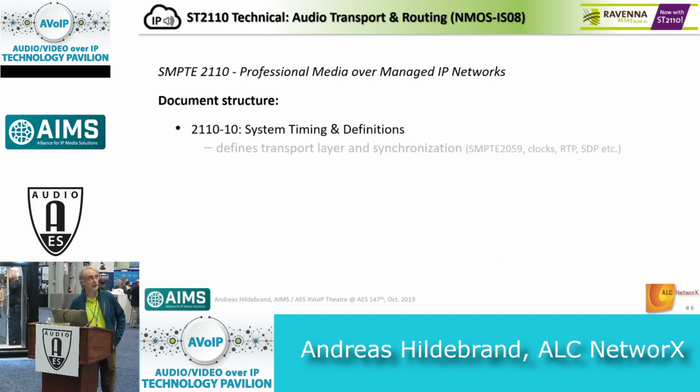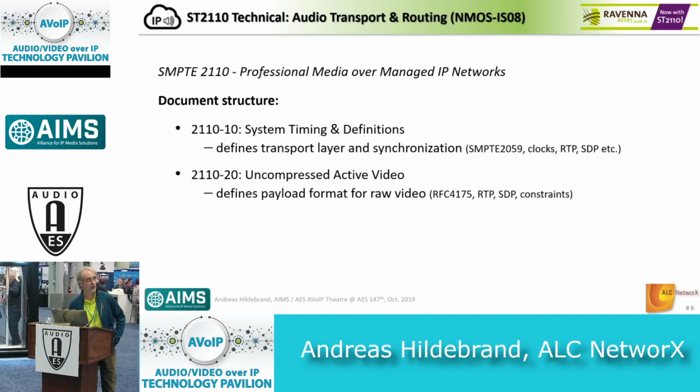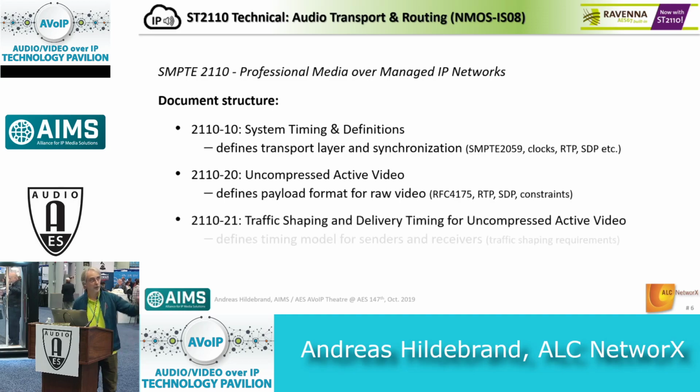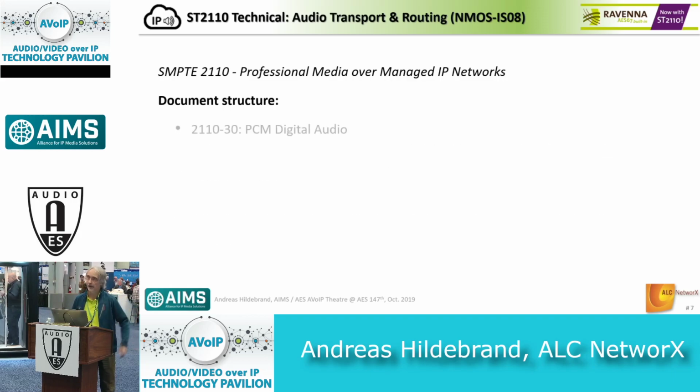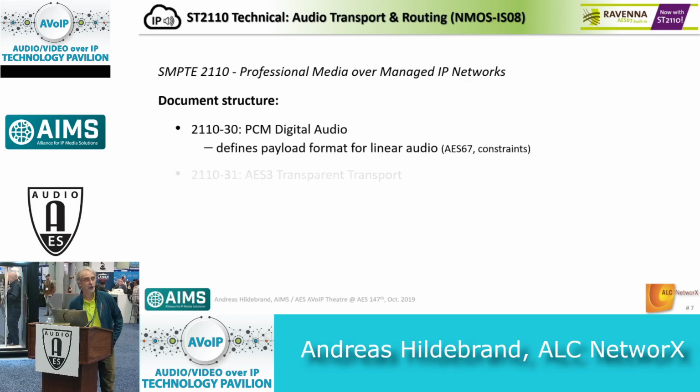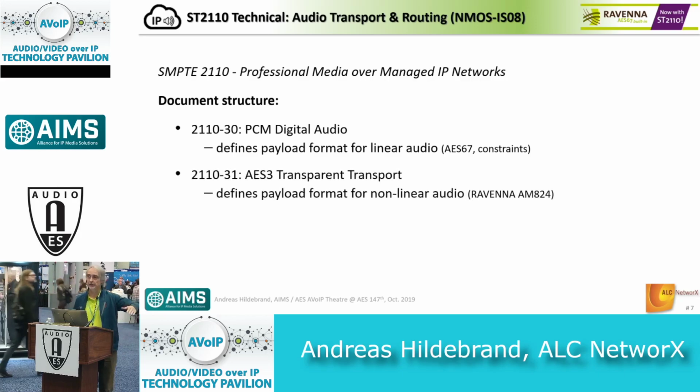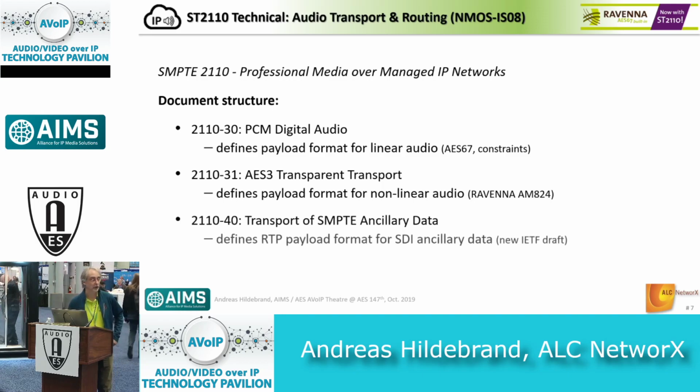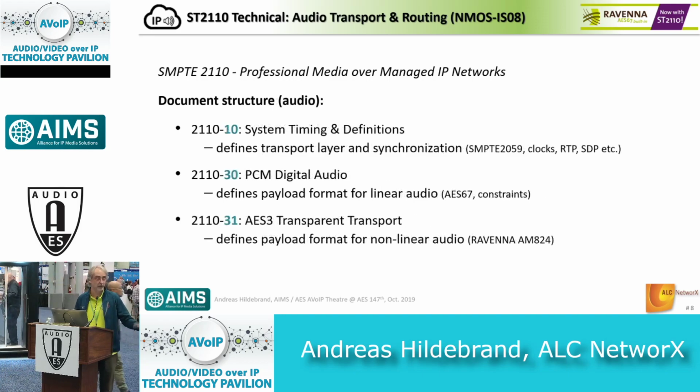So the document structure, I'll briefly explain again. We have -10 system timing definitions, everything which is required to define the transport and the synchronization is in there. -20 defines the uncompressed video, how that has been transported. -21 is about traffic shaping for this high bandwidth video. We have -30 for the digital linear audio, -31 for the AES3 bit transparent audio, -40 for the SDI and ancillary data. And if we look to audio only, and that's what this presentation is about, the audio transport, we have the -10 document, the -30 and the -31, which relate to the audio transport.